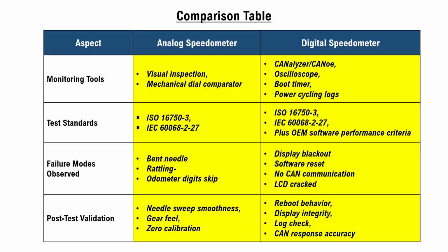Post-test validations. In case of analog speedometer: needle sweep smoothness, gear feel, zero calibration. In case of digital: reboot behavior, display integrity, log check, CAN response accuracy.